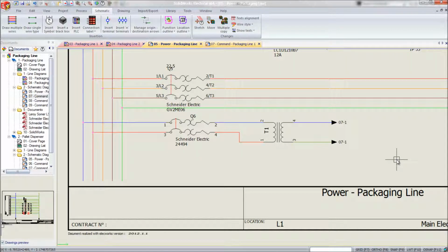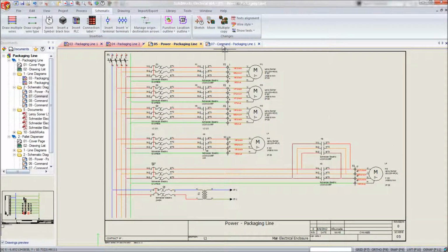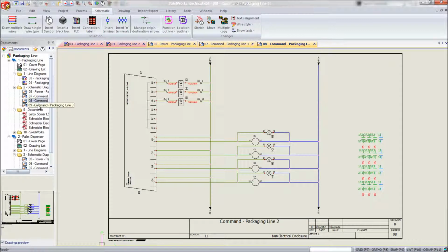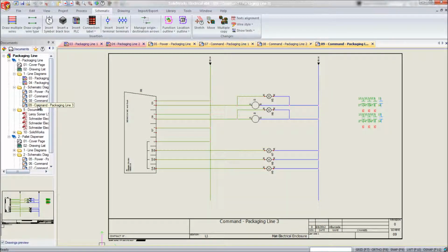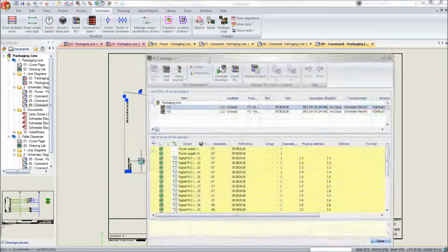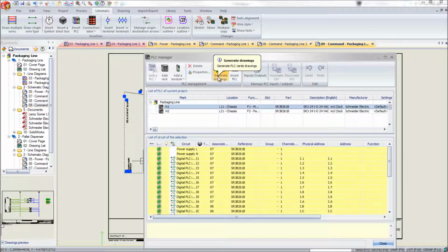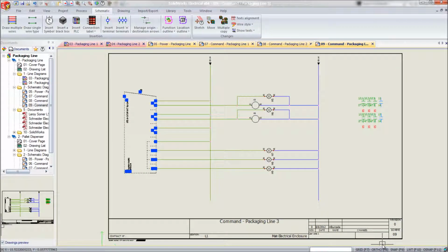In our example, you can see that the packaging line is controlled by a PLC. The functionality of the conveyors and lights is controlled virtually automatically using the sensors and a simple button human interface. SOLIDWORKS Electrical enables you to tackle the development of complex electrical systems with specific tools. PLCs can be inserted or customized like any other parts, and the PLC Manager offers a simple yet concise way to modify it, list the inputs and outputs, type descriptions, add modules, or generate drawings. In addition, macros can be used when inserting a PLC into your schematic to automate the process further.